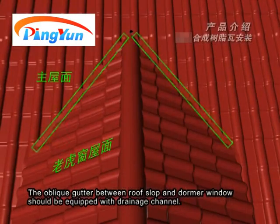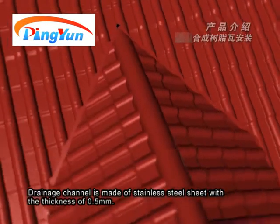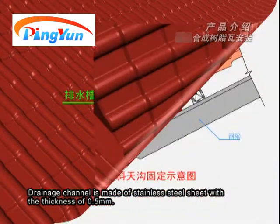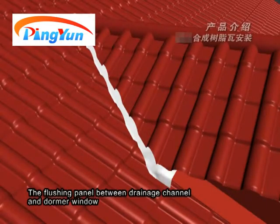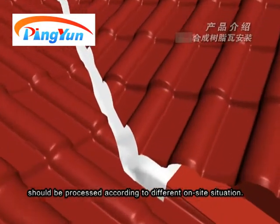Synthetic resin tile is more suitable for vertical type structure. The oblique gutter between roof slope and dormer window should be equipped with a drainage channel. The drainage channel is made of stainless steel sheet with a thickness of 0.5 mm. It is fixed on the purlins of the two-slope roof before the installation of main tile. The flushing panel between drainage channel and dormer window should be processed according to different on-site situations.